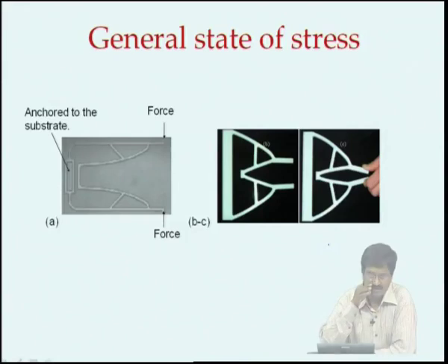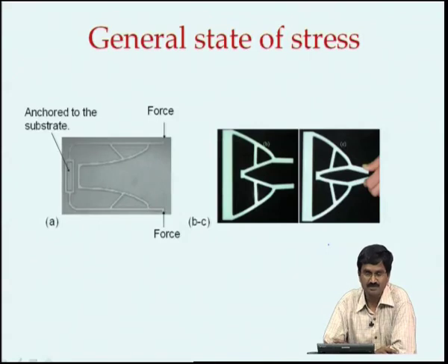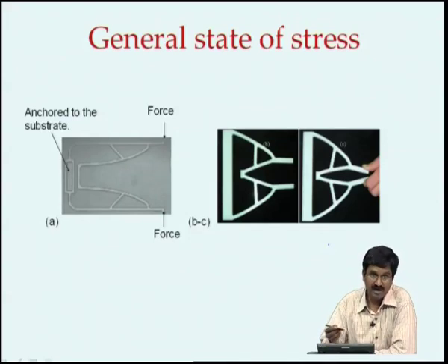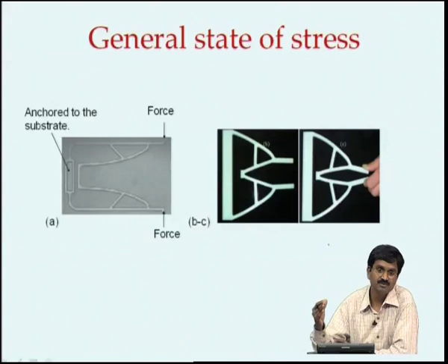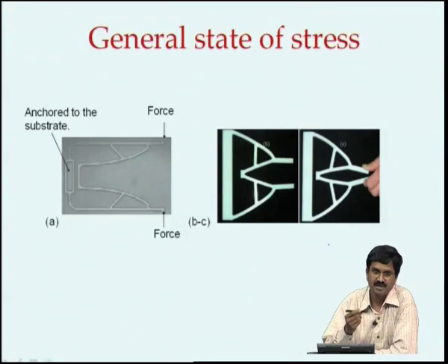We have illustrated the effect of torsion and twist in microsystems, and also did a generic example of a helical compression spring that we see all around us, including our ballpoint pen. We have derived an expression, revisiting Castigliano's theorem to apply it and find a formula. Now, we have also introduced as a process a concept of shear stress. We had talked about normal stress quite a lot, but today we introduced the concept of shear stress, whose effect is only to change the shape of a body, to shear it, where there is a force parallel to the surface, as opposed to normal stress where the force is normal to the surface.